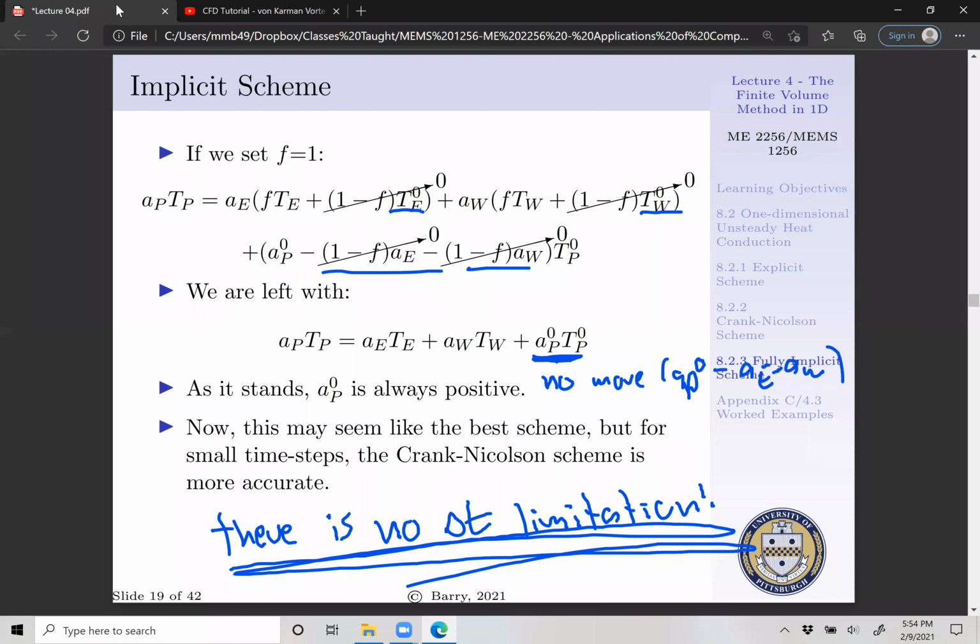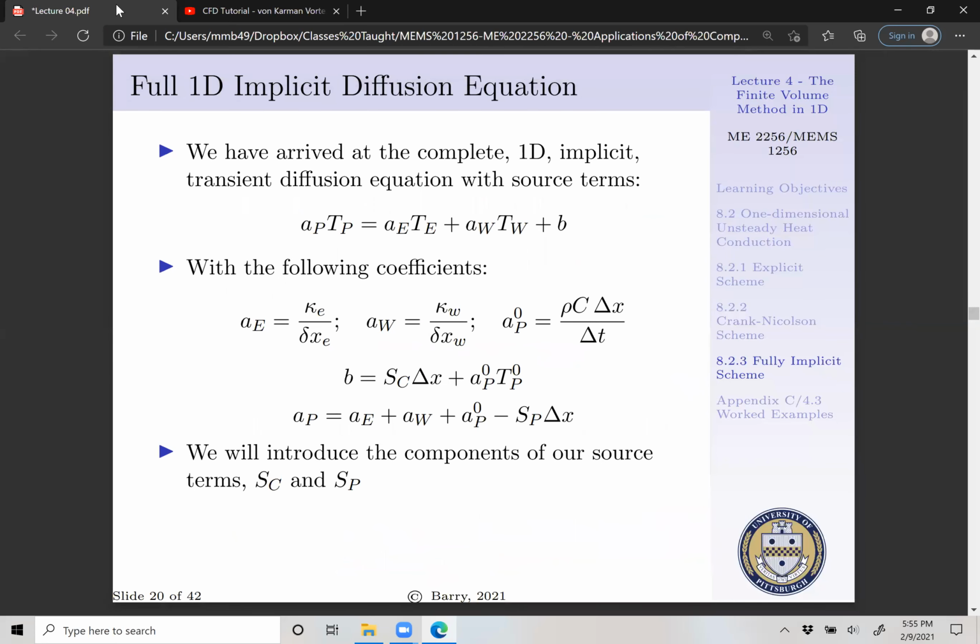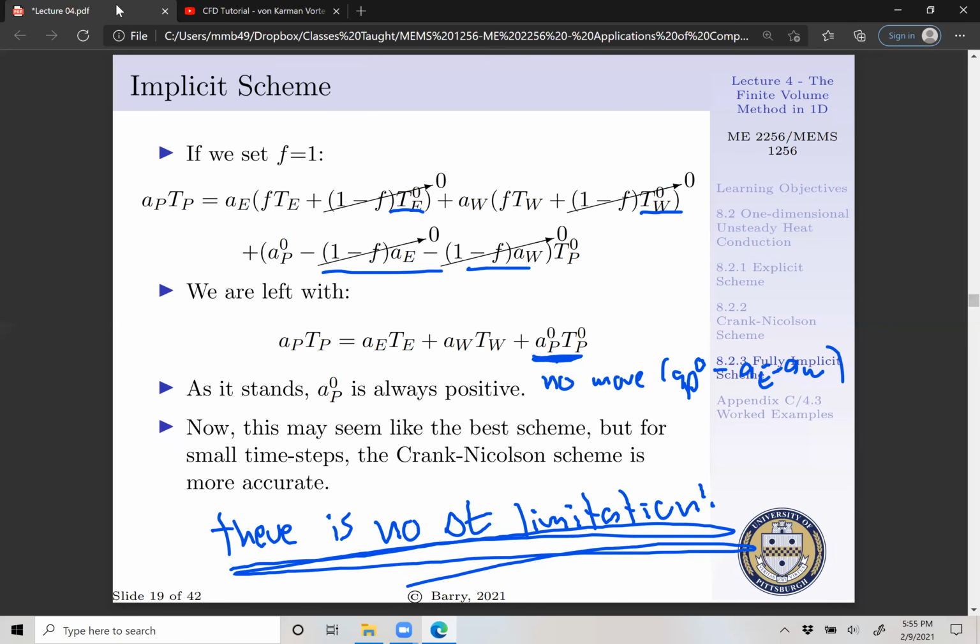If you're trying to capture vortices that are being shed at a frequency of 120 hertz, that means your time step should be less than 1/120th of a second. Probably a lot less to capture the evolution of it as well. Now, you might go, okay, so you can't get something from nothing. That's fair. But it all depends upon the problem you're modeling and what you're doing. And sometimes you just have to figure this out on your own, or spend some time on the forum seeing what's a reasonable delta T to start the problem.